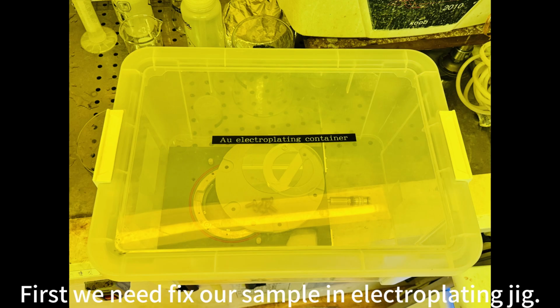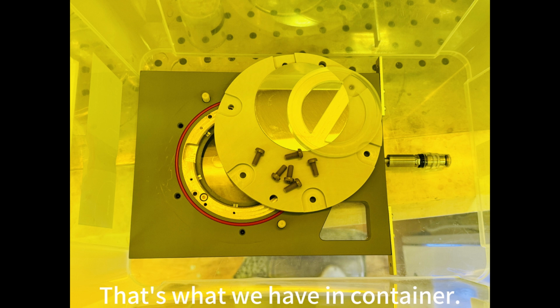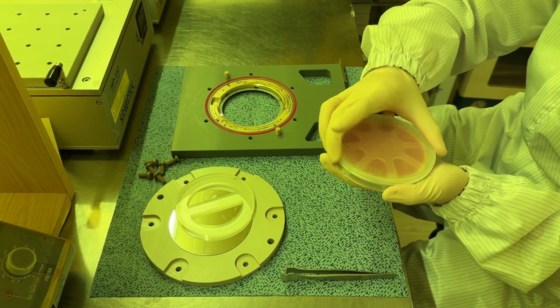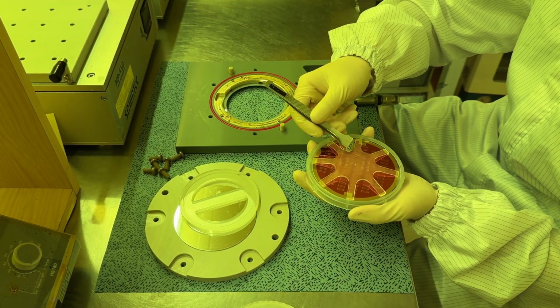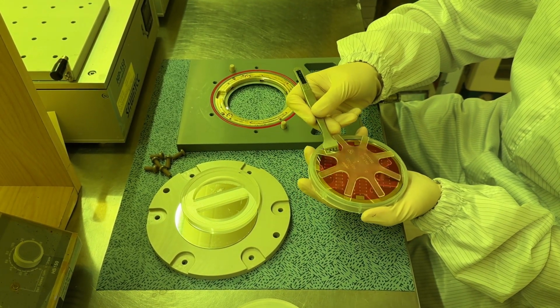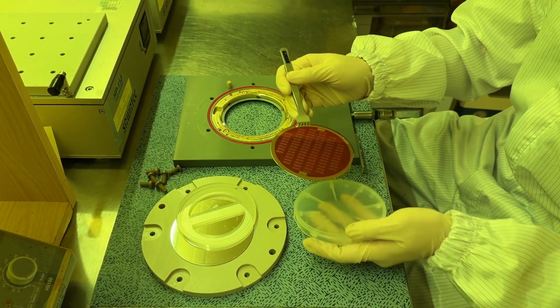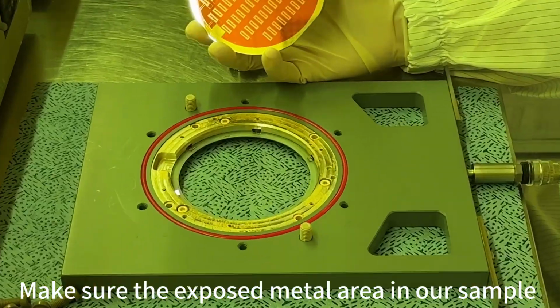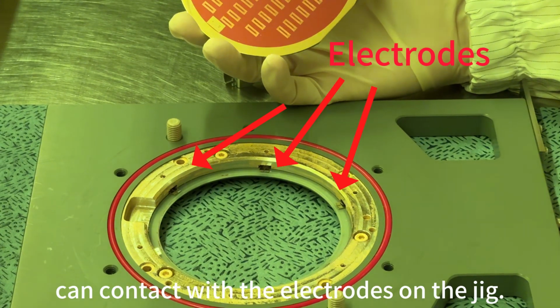First, we need to fix our sample in electroplating jig. The jig is placed in a gold plating container. That's what we have in container. We're gonna hold the sample upside down in the jig. Make sure the exposed metal area in our sample can contact with the electrodes on the jig.